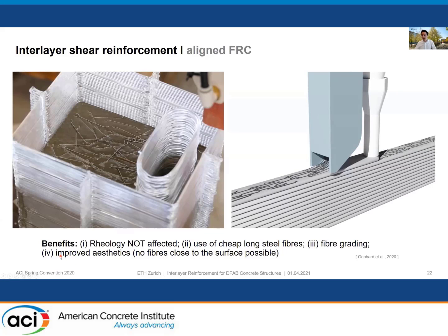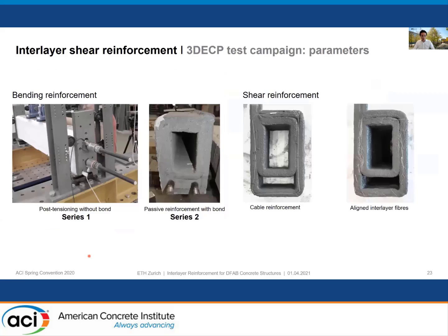Another benefit is that we can leave some part of the concrete close to the surface without fibers. Then these fibers will not rust, which is a static problem when we have steel fibers in the mix. So this is the concept with fibers, and we have done this testing campaign, which I would like to show you a bit more in detail.